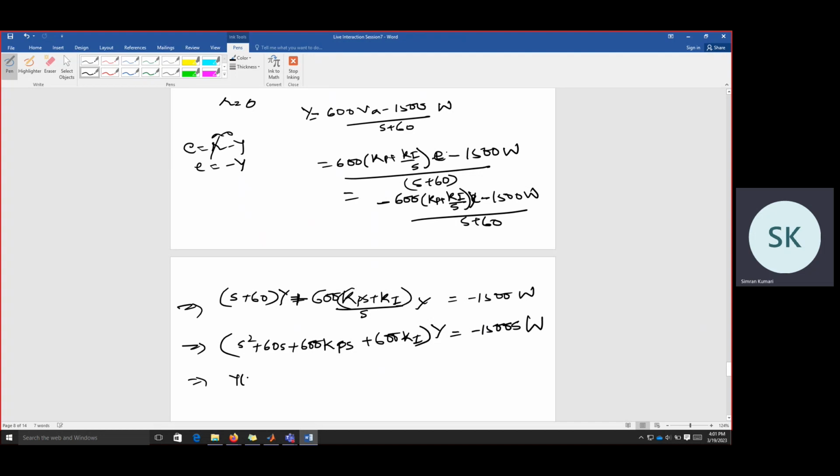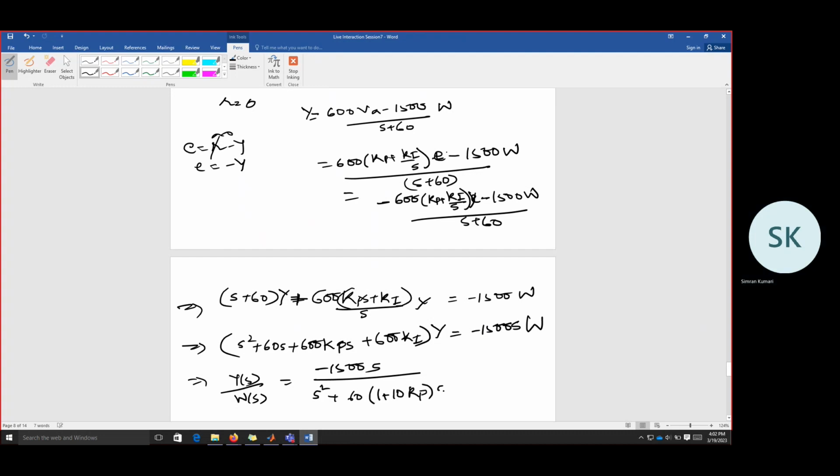So what would be Y(s) by W(s)? This would simply be minus 1500 s by s squared plus 60, 1 plus 10 Kp s plus 600 Ki.